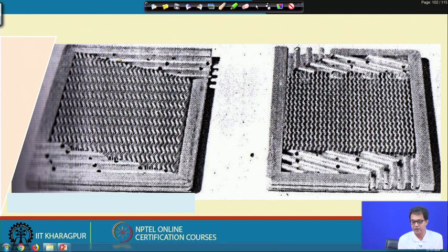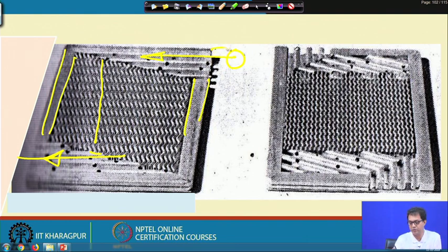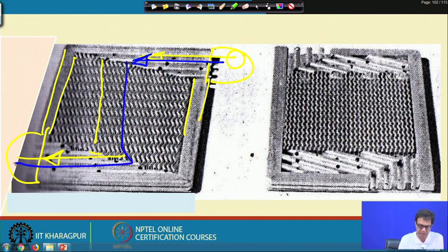Here you can see that this is a kind of perforated fin. In one layer the fluid is entering like this, then it is coming like this, and finally it will move out from this direction. One fluid just on top of it, where are the sidebars? These are the sidebars. So, this fluid is only able to come out from this angle, and it will come out from this end. This is the direction of the flow, this is where it will enter, it will follow this path, then come out from this end. What about this one? Just on top of it, if we put this one, it will come over here, follow this path, and then come out on this side.